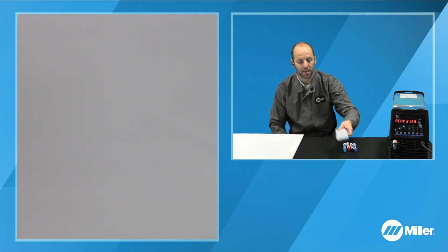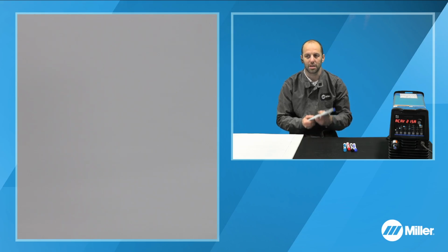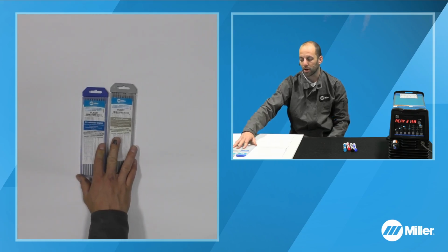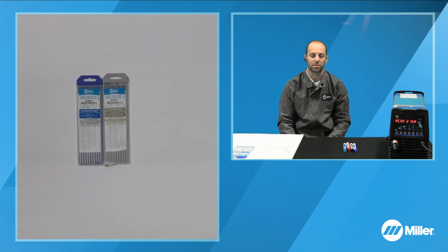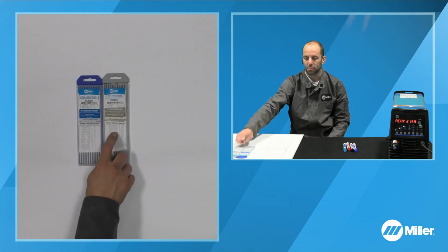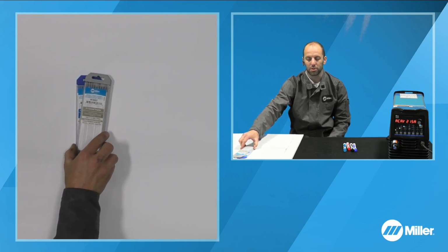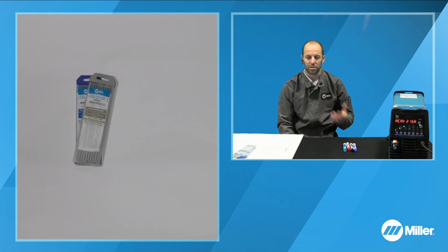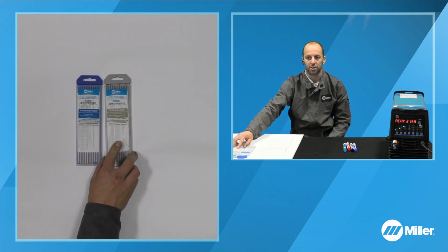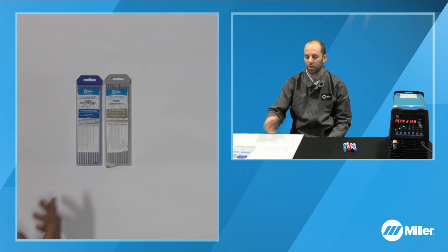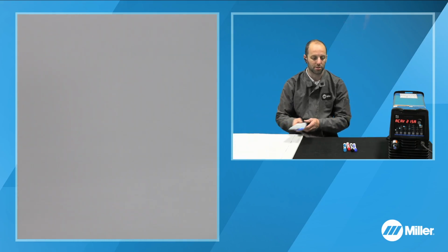One of the things that we want to start with, and it has an impact on your welds, is going to be your tungsten. There are a couple different tungsten types available when we're welding on aluminum. The two most common ones that we recommend with welding equipment used in the industry today, the modern inverter-based power sources, are the 2% ceriated and the 2% lanthanated, so the gray band and the dark blue band. There are a couple different tungsten types available in the industry. You see some of the purple, some of the light blue or aqua, the tri-mix tungstens, and then some people you'll hear talking about the 2% thoriated. But by and large, if you are welding aluminum, these two that we have here tonight are going to be the tungstens that will work for not only an AC application, but also a DC application. So it's a great all-around tungsten that can help you standardize in your shop.